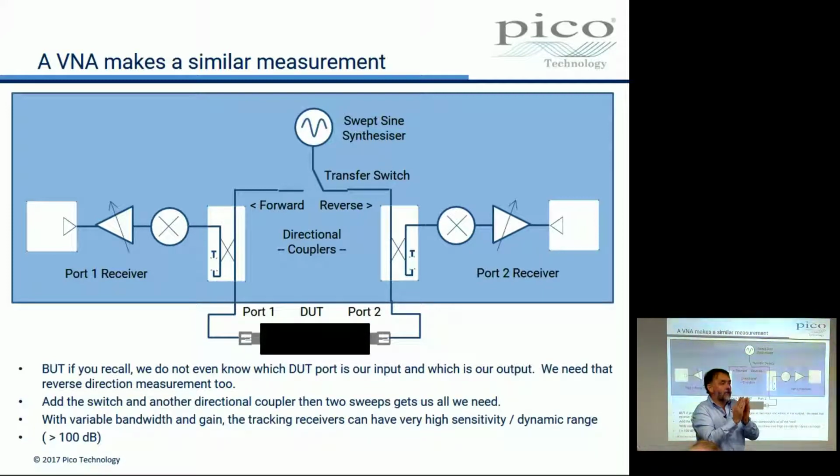And when we look in narrow bandwidths for what's there, we're going to eliminate noise. And so a tuned receiver can be working down to more than 100 dB down. Now 20 dB down is 10 times down, isn't it? And 40 is 100 times down, and 60 is 1,000 times down. So 120 is 1,000,000 times down, right? So you can have a very, very sensitive receiver here if it's a tuned receiver.